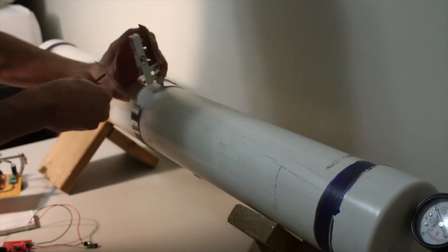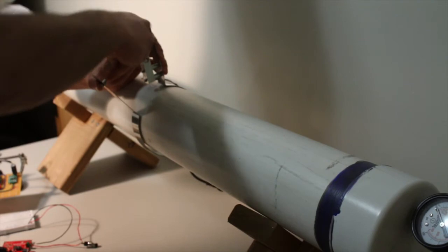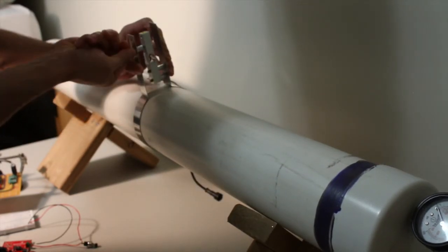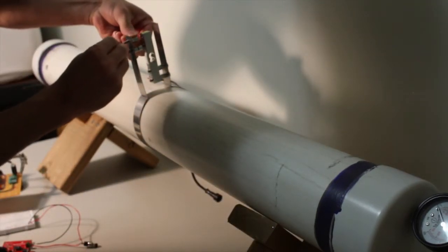Use two hands to gently bring the two arms together and then insert one screw into a hole of the clamp and put the spacers on the other end, between the sensor clamp and the load cell. After a few turns by hand, let go of the clamp while ensuring it is loosely held together by the screw. Repeat the previous steps for the second screw.